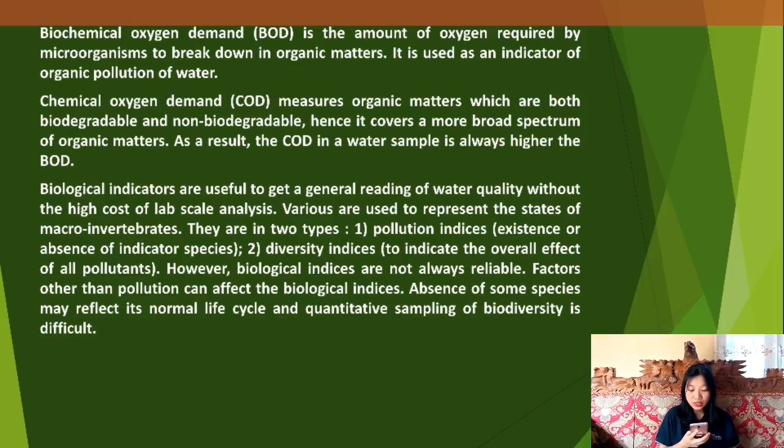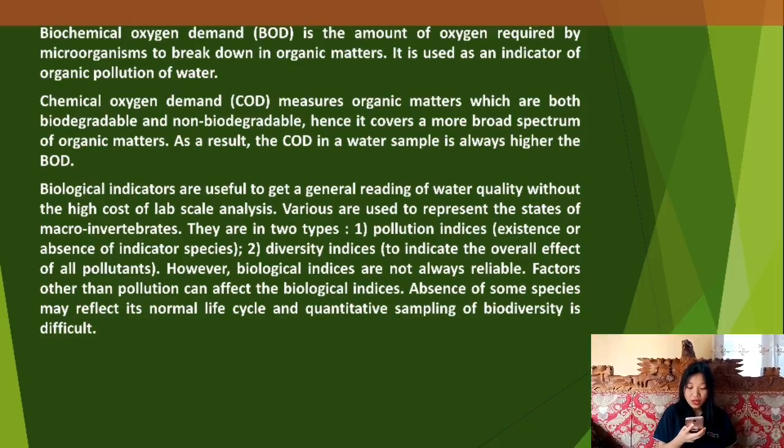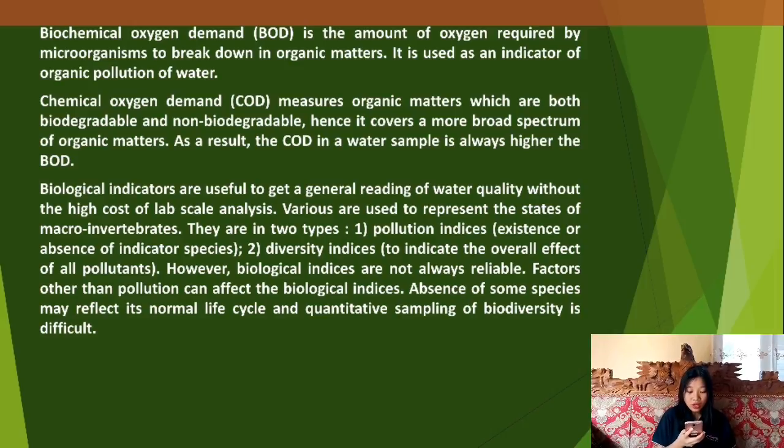It is used as an indicator of organic pollution of water. Chemical oxygen demand (COD) measures organic matter which is both biodegradable and non-biodegradable, hence it covers a broader spectrum of organic matter. As a result, the COD in a water sample is always higher than BOD.